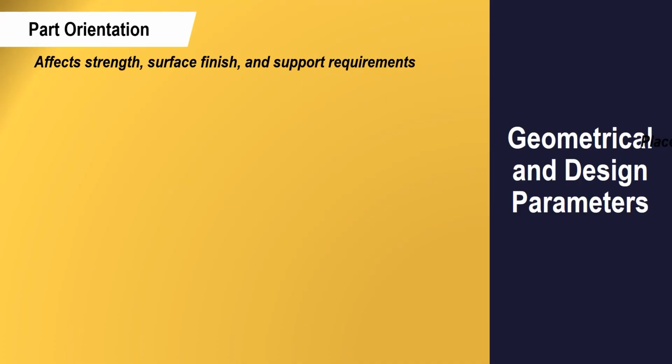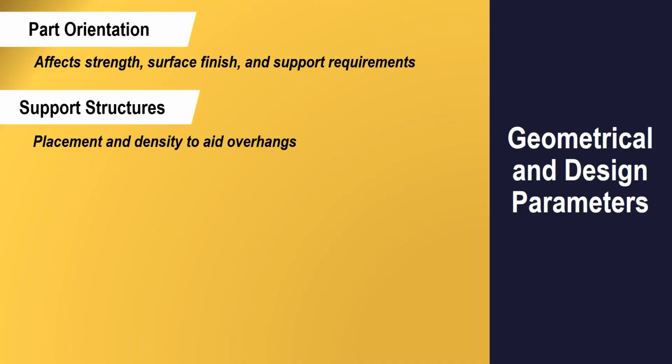Then coming to the support structure, of course, the placement of the support, which is either consumable, or a water-soluble type I am using. If I put it at certain places where the quality of the part is not compromised once I detach it, there should not be any functional barrier over there, right?